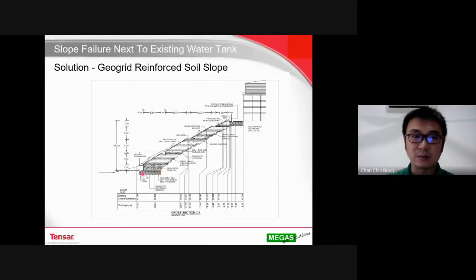So in this section, as far as replacement is concerned, you see this legend, we fill up the sand for the wall, followed by the sand column, and we will terminate it before the second slope. Then the same idea again. Okay, we have sand layers and then sand column, sand layers, sand column. All these sand layers and sand columns are to facilitate, if there's any water at this level, it will go into the column and it will be able to drain up to the berm drain and discharge away from the slope. Okay, so same thing over here. And I would like to highlight that, remember, if you do details like this, always do not connect your drainage layers or columns all the way up to the top platform. Okay, we terminate at each slope so that it is able to drain away the water from the slope as quickly as possible. Okay.